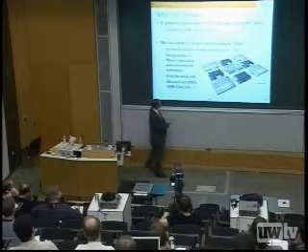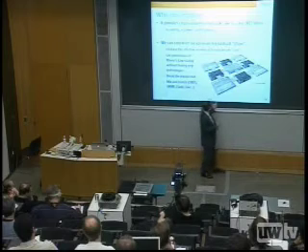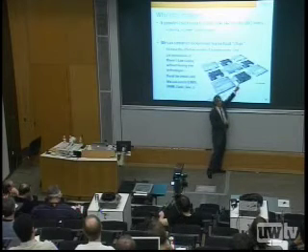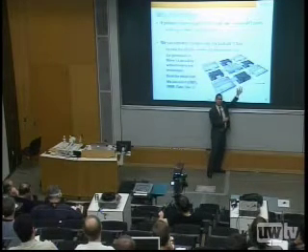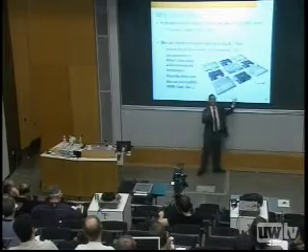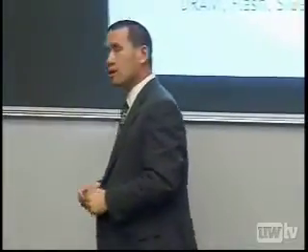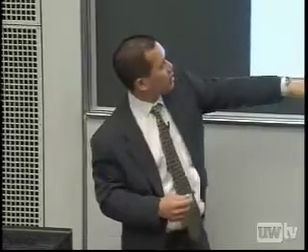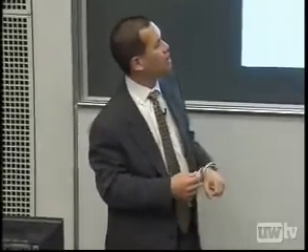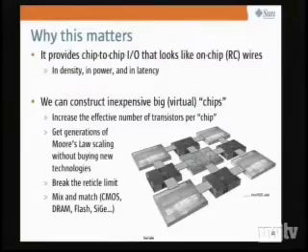What's even nicer is that I can do this and mix and match technologies. If I want memory, I'd really want DRAM. Right? I want a DRAM process. I don't want an SRAM process because that's not nearly as dense. It's 30 times less dense than DRAM. So I can mix and match a DRAM technology with a logic technology, maybe some sort of SiGe technology for other kind of wireless systems, and I can assemble these into one coherent whole.